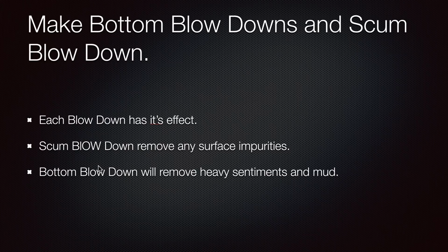But for the bottom blowdown, you can have your boiler off and you make it for 20 or 30 seconds. But before you do that, open your lines, heat up the line slowly by blowing down the line a little, and then open it to the full. You can hear a noise from the line when you're opening to the full, and this is how fast your water flows.